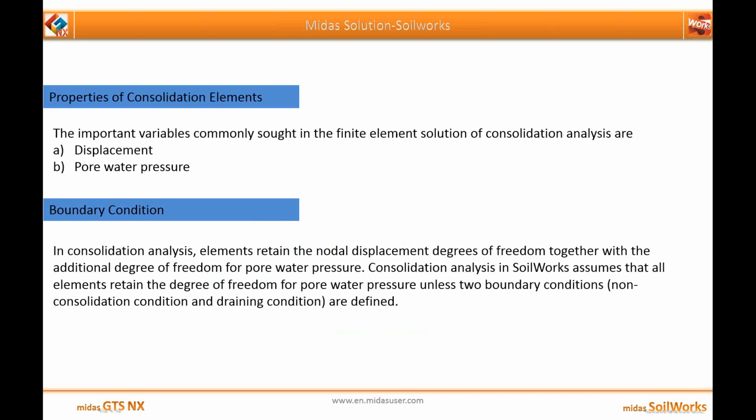Now, the properties of consolidation elements. The most important variables commonly sought in the finite element solution of consolidation analysis are: first, displacement, and second, the pore water pressure variation. Now, boundary condition. In consolidation analysis, elements retain the nodal displacement degree of freedom together with the additional degree of freedom for the pore water pressure.